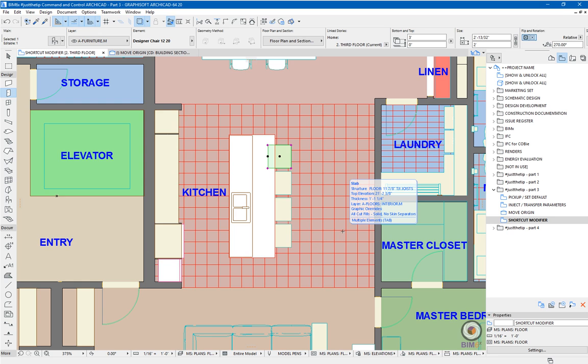I've zoomed to this different area so we can show this example. This is Alt-E, E for element snap, and what it allows me to do is, if I've got something selected and I start to maybe drag, for example, you'll see there's the various node points that highlight, and what that wants to do is snap to other elements.